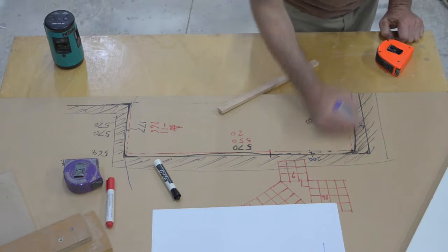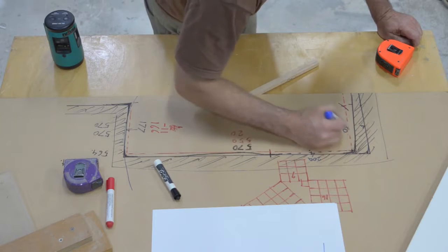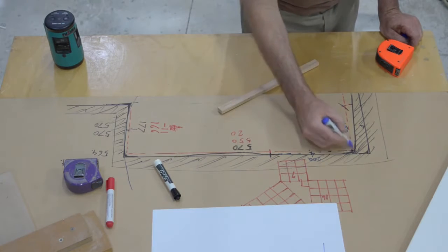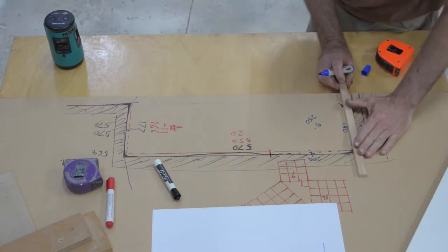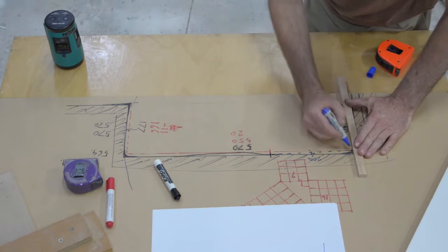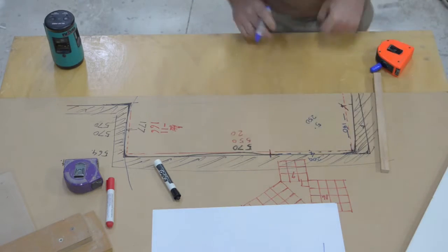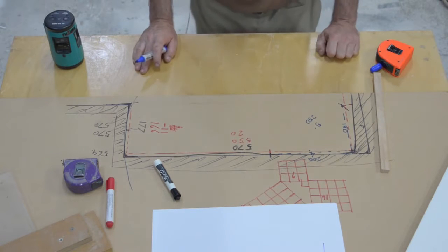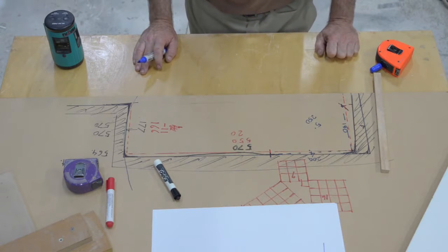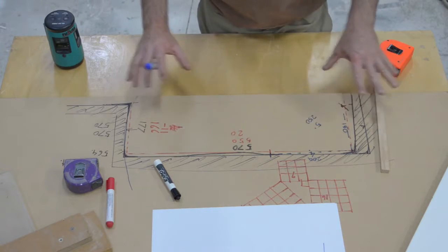Now we come out from that same point, 150, which is 3 times our 50 millimeters, and it gave me a point over here. But as you can see, even though I think I've made a square line, I've made it square to this portion. I haven't made it square to the whole line. So it becomes very tricky to assess on site what actually is square. You've got to make sure you're taking enough information in.